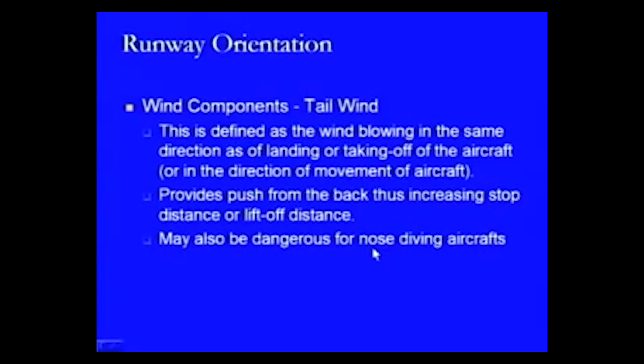And if that type of aircraft is standing on the apron or in the parking area or bay, then in that case what will happen is that the tailwind which is coming from the tail direction will create an effect of a sort of a lift from the back side, and the nose will go further down and will hit the ground. So, that is a dangerous condition for that aircraft, because then the aircraft will become unoperational in this sense.